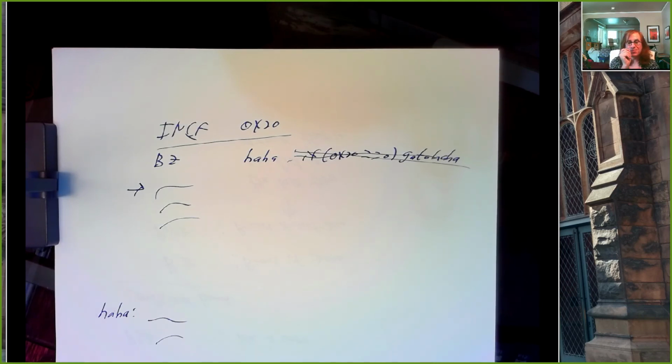And we'll make that really specific next, but you get the general idea of what this conditional branch is trying to do. So basically it triggers a 0 flag. So if I were to make an instruction like increment so that a file register became 0 and then jump to the branch if 0 instruction, if I knew exactly where it was in memory and I jumped to it even though it wasn't sequentially down the line, it would still trigger it, right? That's right. Nice.